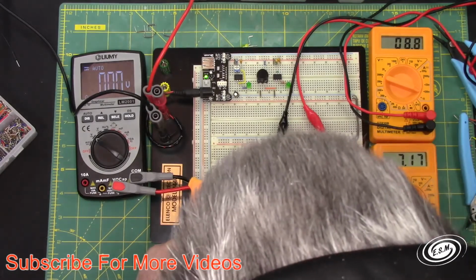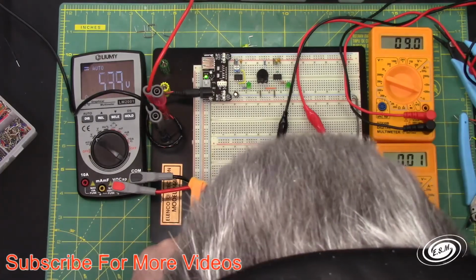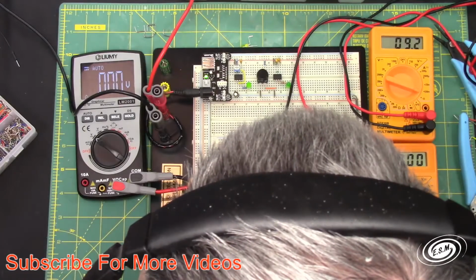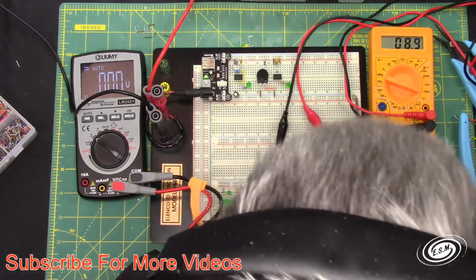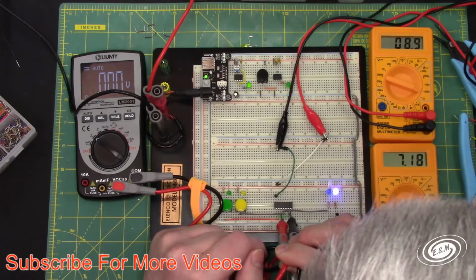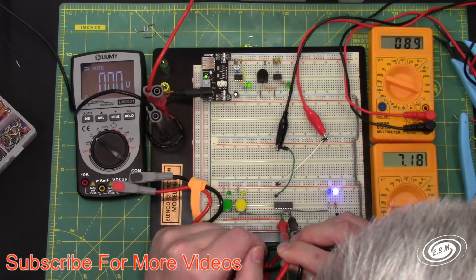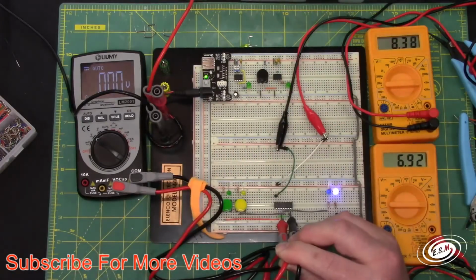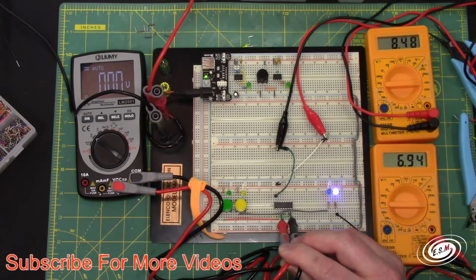But if I pull that voltmeter out, it won't work. So we're going to put it back in and we're going to measure the current and see what the quiescent current is. So it is 9 milliamps. So let's put it back on here. So 8.6, 8.7, and 6.9 on the LED. So it's drawing a good milliamp.